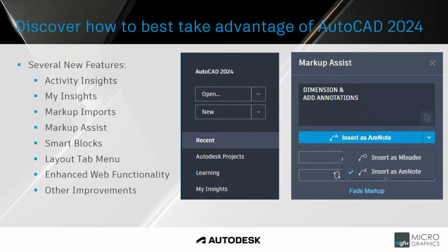When Markup Assist detects instructions within the markup text, for example move, copy, rename, delete, whatever was handwritten or typed on the PDF, you can select that text to start the associated command. AutoCAD recognizes certain words and you can immediately just select the written text inside your workspace.